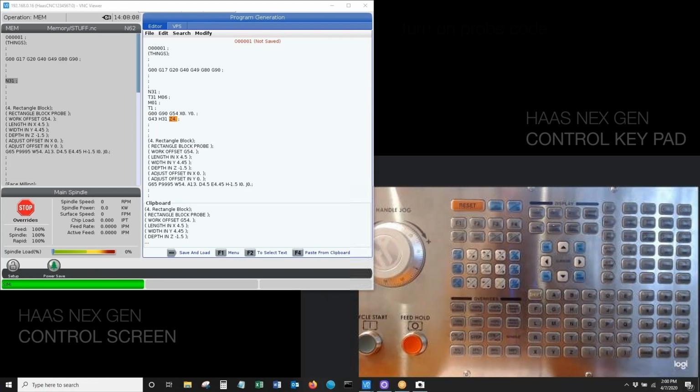Remember, this is a rapid position point, and it's not protected, folks. We have not turned the probe on yet, so we want to stop somewhere nice and high above the part, somewhere nice and safe, and somewhere we're not flipping out to hit the feed hold or the reset or the e-stop in case we see something that we don't really like.